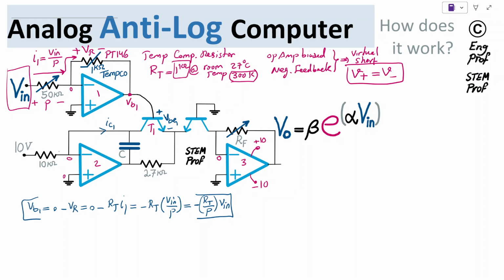Now this current is coming through the 10K resistor, because whatever current comes this way has to continue this way. Again, it cannot flow through the input terminal of the ideal op-amp, because the input terminal of an ideal op-amp has practically infinite impedance. So how do we calculate this IC1? Well, on one side we have 10 volt, on the other side we have 0. So I can easily compute IC1 as just 10 volt, the voltage drop across the 10K, divided by 10K.